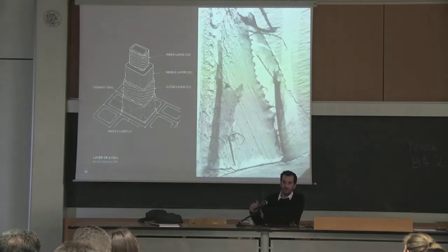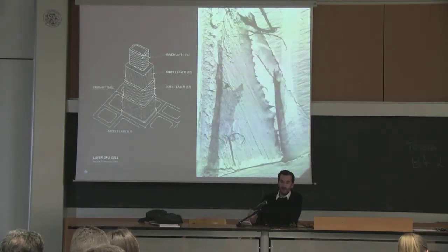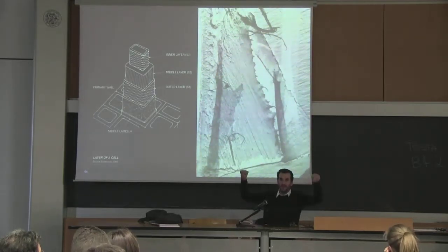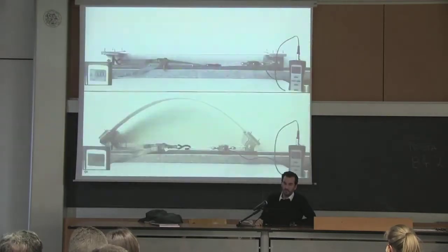That's also why a lot of wood products have been replaced by glass fiber products, like skis and the vaults for pole vaulting, all these kinds of things. What is particularly interesting for architecture is that these materials all have a high level of strength combined with a low level of stiffness, which means that you can elastically bend them and they still have a structural capacity.